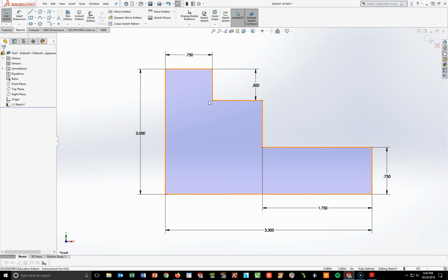This is really, really important to understand. SolidWorks wants every sketch line to be black because what that tells it is that this part is fully defined. And how do I know for sure? Because down here in this lower right corner, it says fully defined. One of the things you've got to do when you work on these problems and you start these sketches is all sketches must be fully defined. If they're not, you're going to have a problem with your mass in the end.